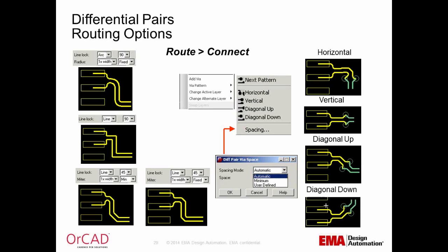When working with differential pairs, you will see a DRC flag with the initials DU if the uncoupled length exceeds the maximum allowed. You will also notice that the line segments that are in violation have become highlighted, making it very easy to find and correct them.